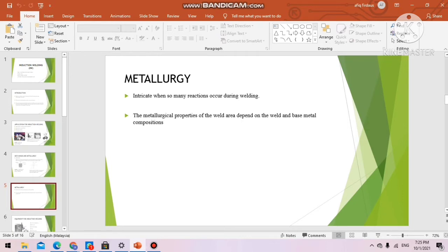Thus, in the fusion zone, different kinds of stable and metastable phases of ferrite and austenite are evident. Higher heat input, for example, can initiate the formation of ferrite to be denser in a welded metal and increase the grain structure size. The welding parameters can be regulated to regulate the properties of the microstructure, which significantly affect the mechanical properties of the welded component.